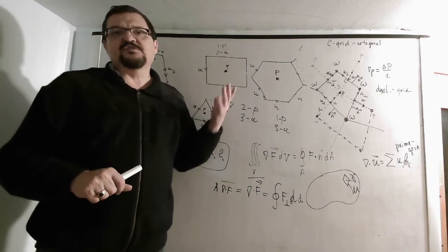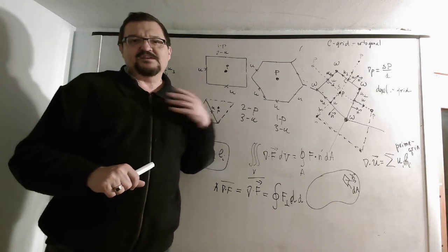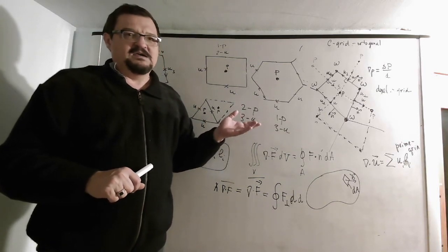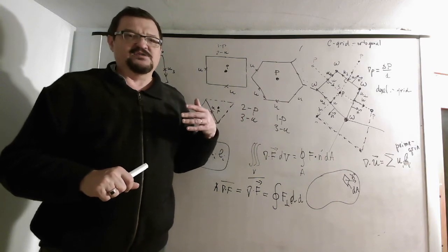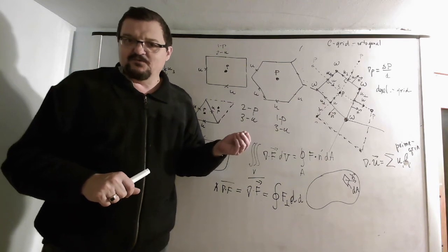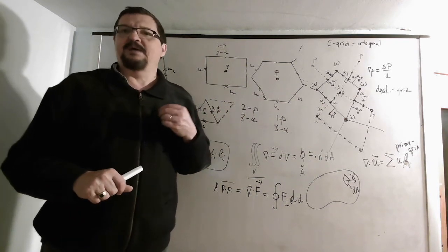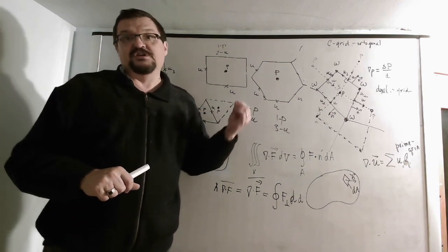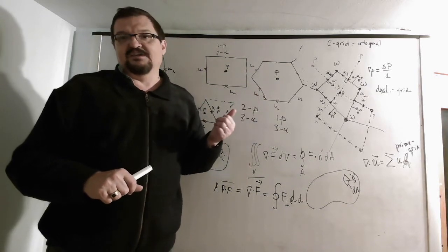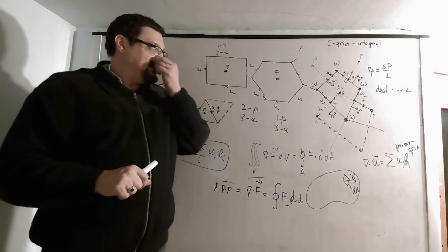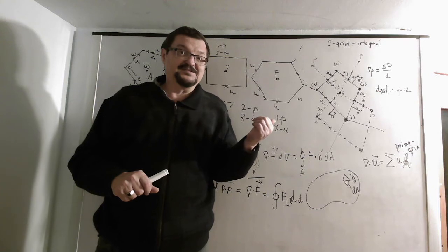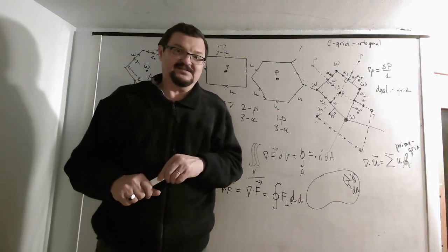So there are some methods to filter them and stuff like that. But as soon as you start filtering your solution, you're effectively losing your resolution, your effective resolution. If you make your solution smooth, then you don't really need that high resolution grid anymore. So that's always a bad thing, to filter your solution just to get rid of some disturbances, especially if they are computational modes. Because by filtering these computational modes, you may be filtering your physical solutions as well on these small scales.